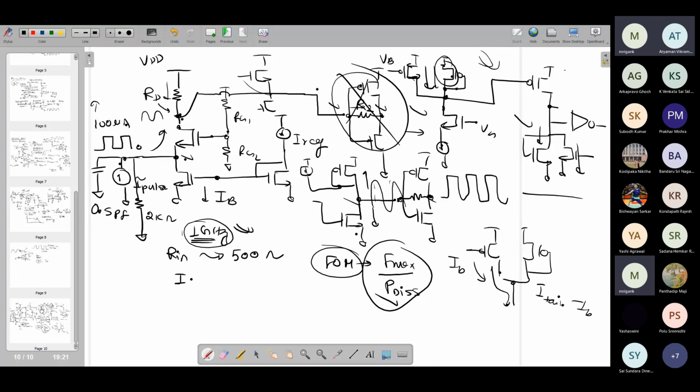So the gain part, I think it will be required, because with the common source stage I was getting a maximum gain of around 15, 20, 10 to the power 4. I think by itself without cascode may not be possible. So you have multiple stages over here. Cascode will not be possible because the frequency required is very high. So common source you can still get large gain provided you use a very large impedance and the bias current is small.